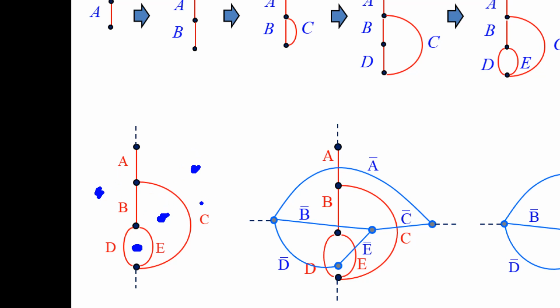After that, you connect by adding an edge or line between this node and this node. The line that cuts or intersects this line controlled by A means this one is controlled by A, also active low. Then you connect this point and this point together, because this line intersects this line controlled by B, that means this line must be controlled by B bar, controlled by B with active low,